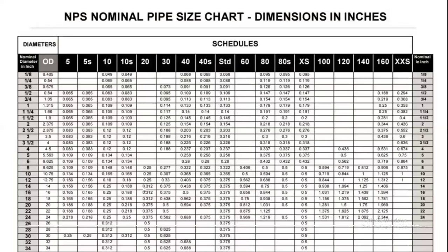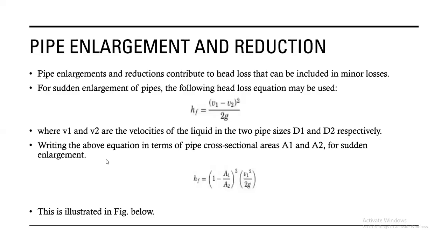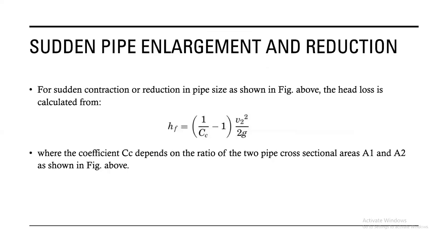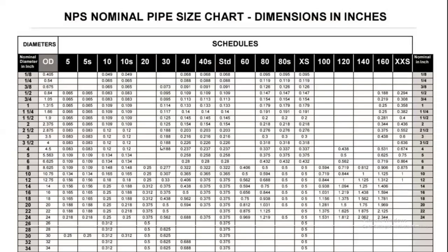So remember, we were told that the valve is 6 inches. I'll come here, then if you remember, we used a diameter of 6.625, and if it's schedule 10, where they intersect is 0.134 thickness. We also used a 20-inch schedule 10.